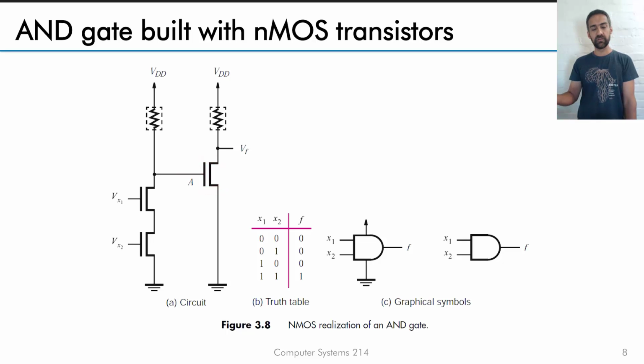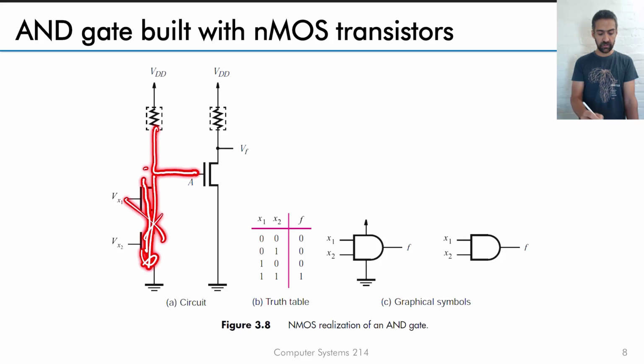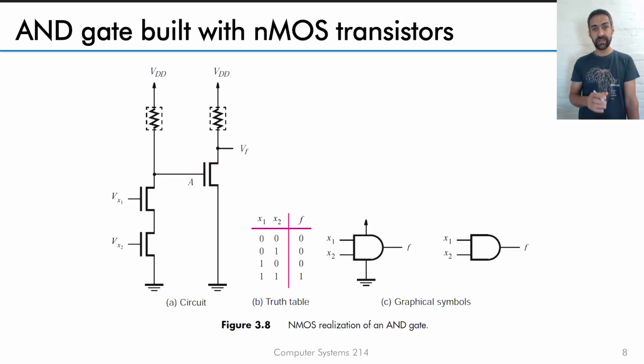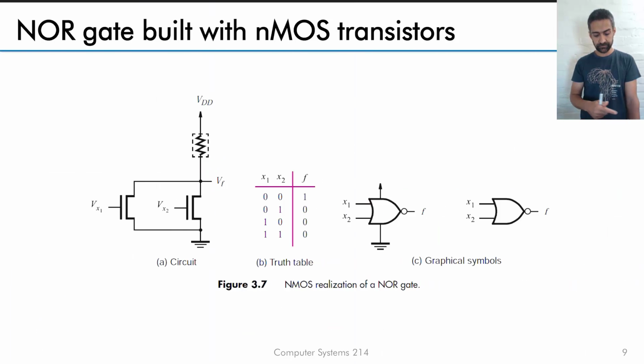It's a field effect transistor, meaning it works with voltage, it doesn't work with current, and because it doesn't draw current, there's virtually no current flowing here when this path here is killed. So if no current flows through here, the current that flows through here is minimal because the impedance that this device presents as an input impedance here is virtually infinite.